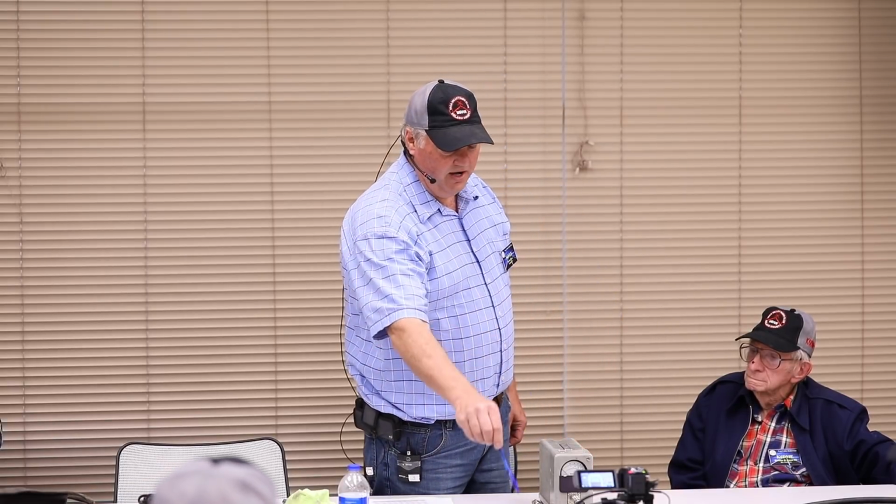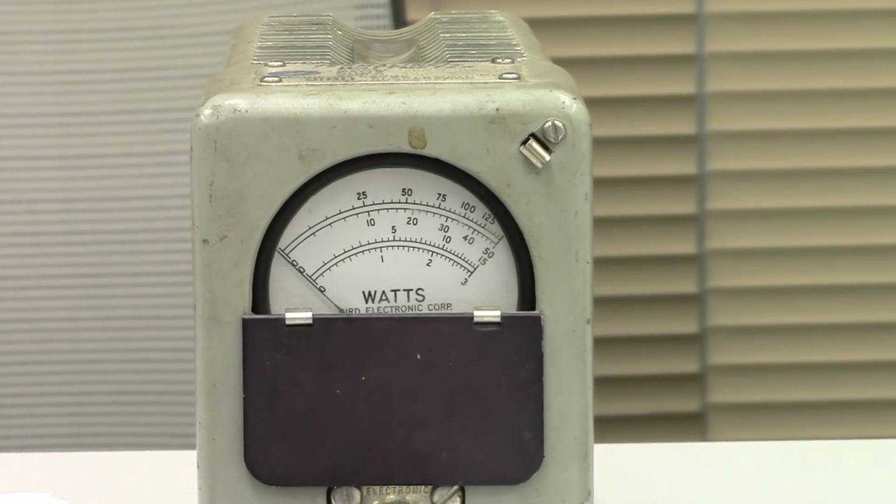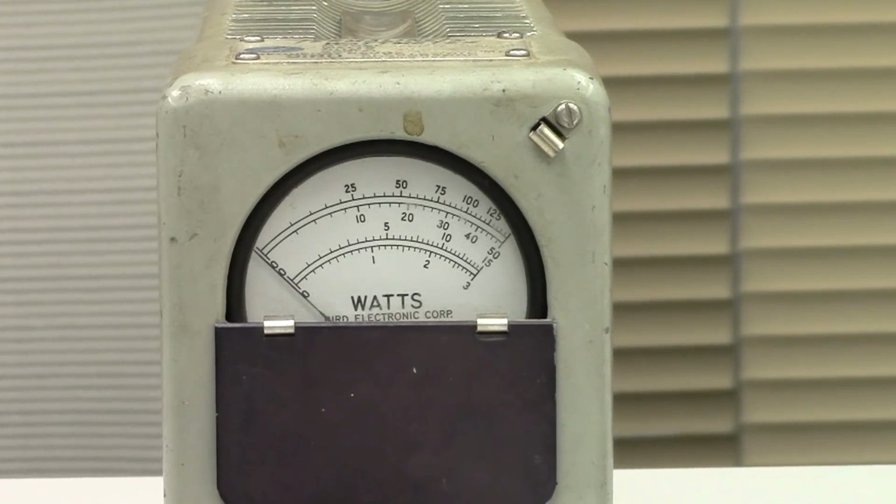The reason somebody asked, why would we care about our coax? Because your coax is your transmission line that gets the energy from your radio to your antenna. In this case, our fake antenna, this guy right here, the dummy load, the Bird dummy load with a wattmeter in it. If you can't get all the energy from your radio to the antenna, and there's losses in between, it's going to degrade your signal on the transmit and the receive. It's not one way, it's two ways.